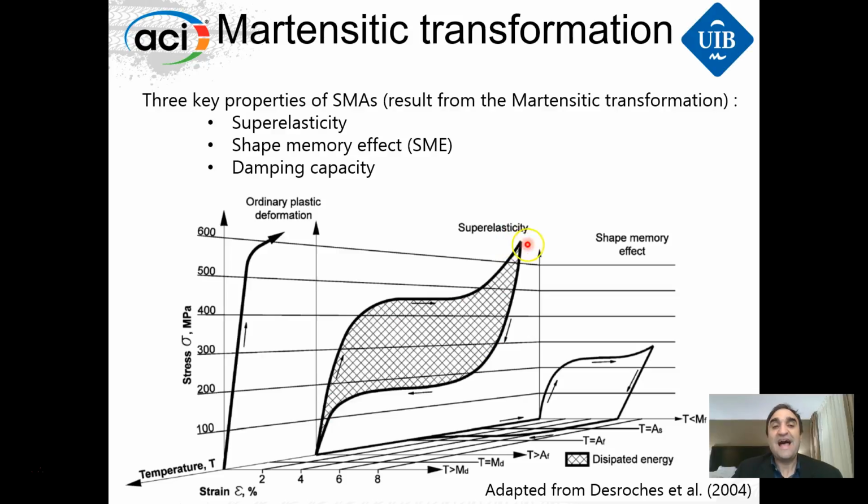and different applications. And then we have the shape memory effect. You can see here the shape memory effect. We are going to play with the stress, the strain, and the temperature in this axis here. We can pre-strain a sample. If we have it in a martensite state, we can load it and then unload, and we will have some kind of permanent strains, but they are not really permanent. Then when we heat the material, and then we cool the material, we go to 0 strain.